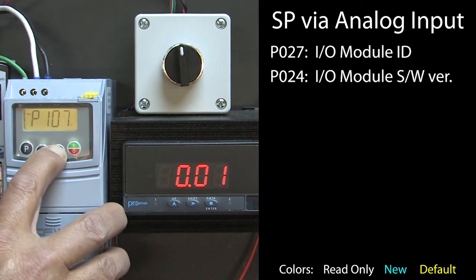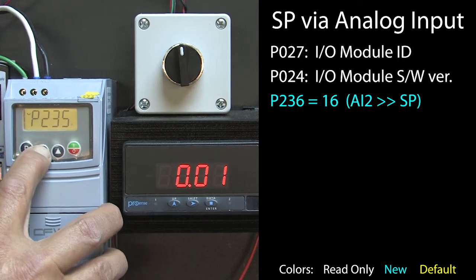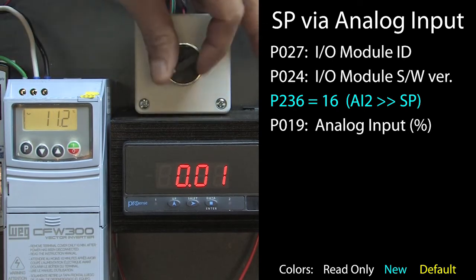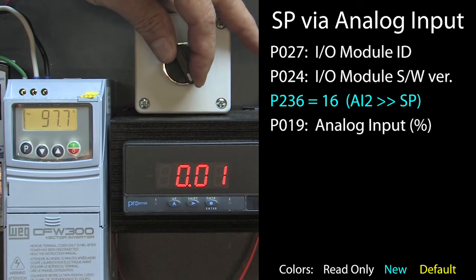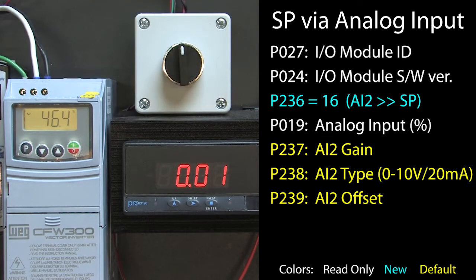Given that the module is recognized by the drive, let's go to parameter 236 and set it to a 16 to tell analog input 2 it'll be used as a set point. Now we can go to parameter 19 to verify that the drive sees the raw analog input. Looks like we can go from 0 to 97.7%. That's good enough for this demo, but if we wanted to, we could tweak the gain of the analog input to get the full 100%. I'll put this back near the center of the range.